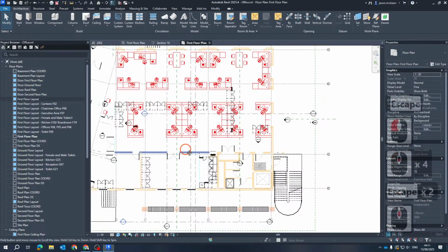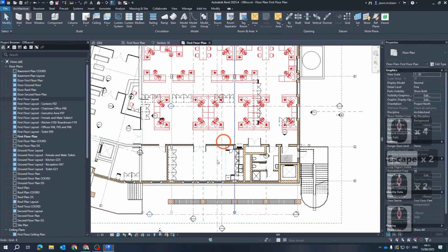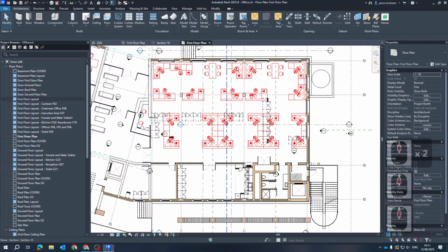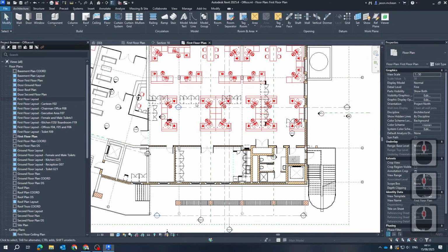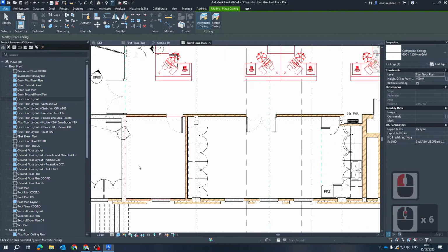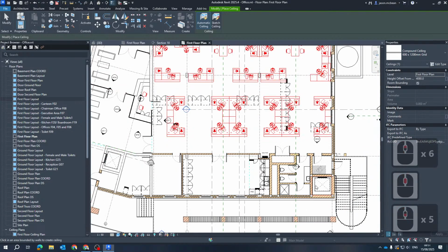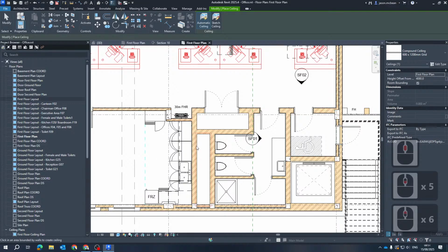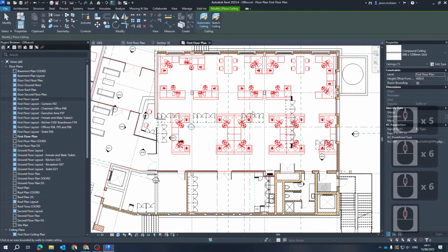Once you've set up and divided your rooms, if you want to create ceiling plans, they use the same room convention. If you go to Architecture and Ceilings, in automatic ceiling creation you'll notice that it finds these rooms. You'll see it creates a red line around the rooms that it's trying to encircle. So this is a quick way to put your ceiling plans together.